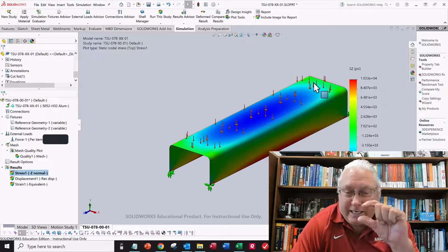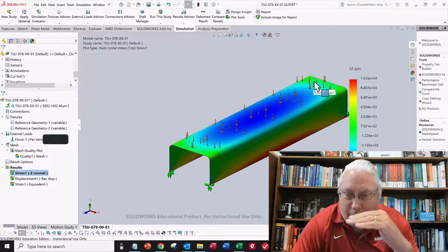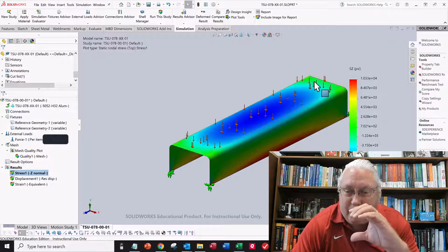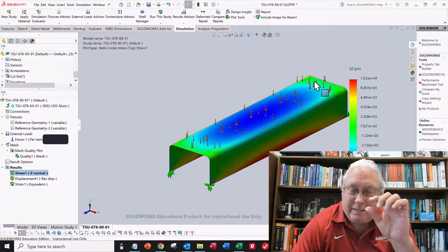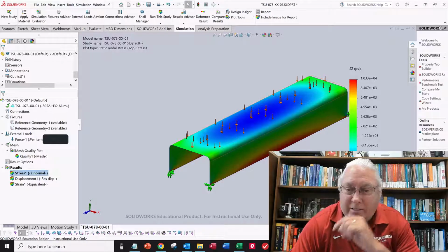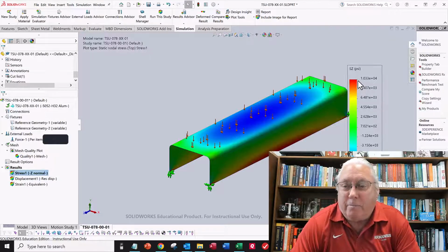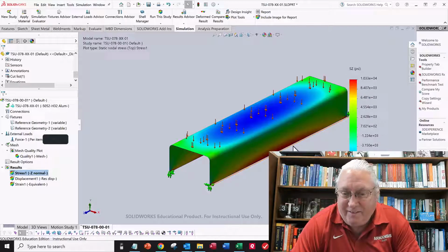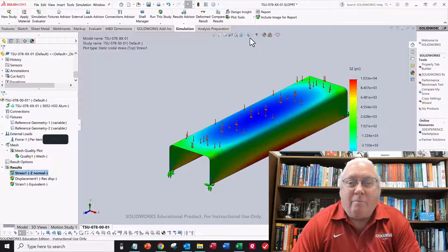And that's because that C_XX value, remember, the distance to the bottom edge was further from the neutral axis. The distance to the bottom edge was bigger than the distance to the top edge. So both of them have stresses, but the maximum values are going to be here at the bottom, which are shown here in red.